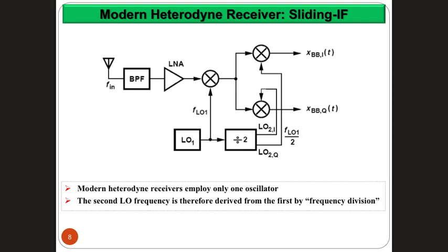In addition to that, oscillators also tend to create a problem that we'll discuss in the next few slides, that they leak back into the input of the system. We'll see why this happens and how to overcome that problem, but it will come later. So in general, we want to minimize the number of oscillators in our RF design.